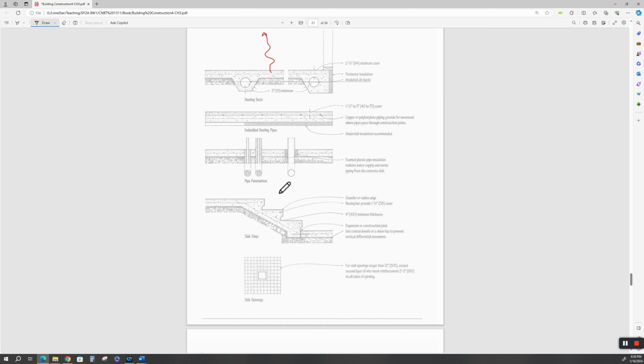Pipe penetrations through a slab are a problem, especially down here where we have a lot of termite problems. Those things need to be sealed, and they need to have a way of getting in and inspecting them to see if termites are damming up into your structure. Even if you put foam plastic insulation and seal all this stuff. All right.